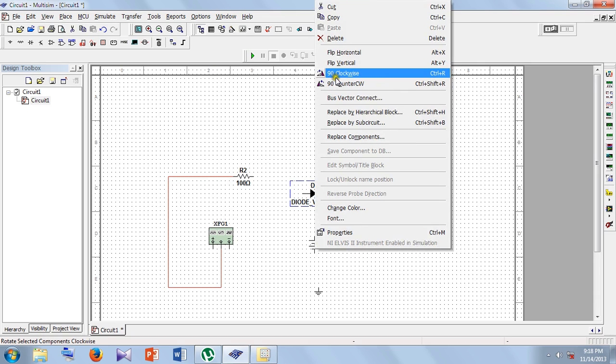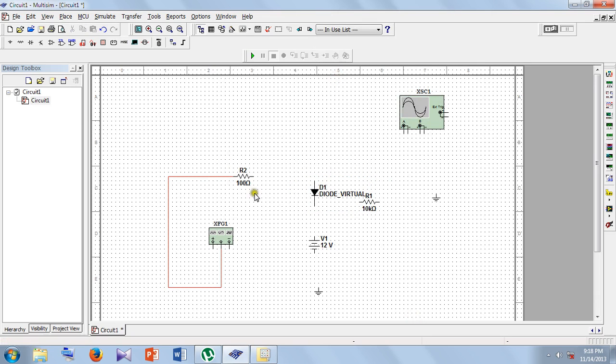Next, you invert the diode. You connect it using a wire. Next, from diode negative to positive of the V reference, and negative to ground. And from negative of the function generator you must connect to ground.